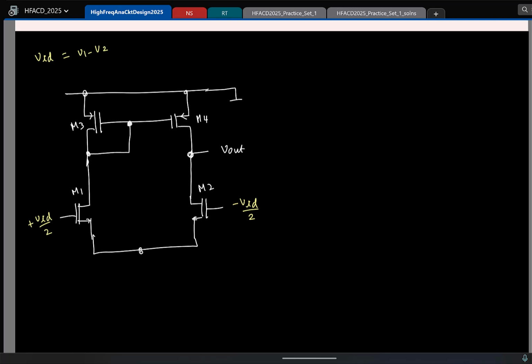Let us say if this was a circuit like this, what would be your first conclusion? How will you make the circuit symmetric? All the nodes along the line of symmetry are 0. Again, this we saw for any linear network. If you have symmetric linear networks like this, and we have anti-symmetric excitation, by linearity and superposition we can conclude that these two nodes will be 0. But right now we cannot say that because you have this asymmetry.